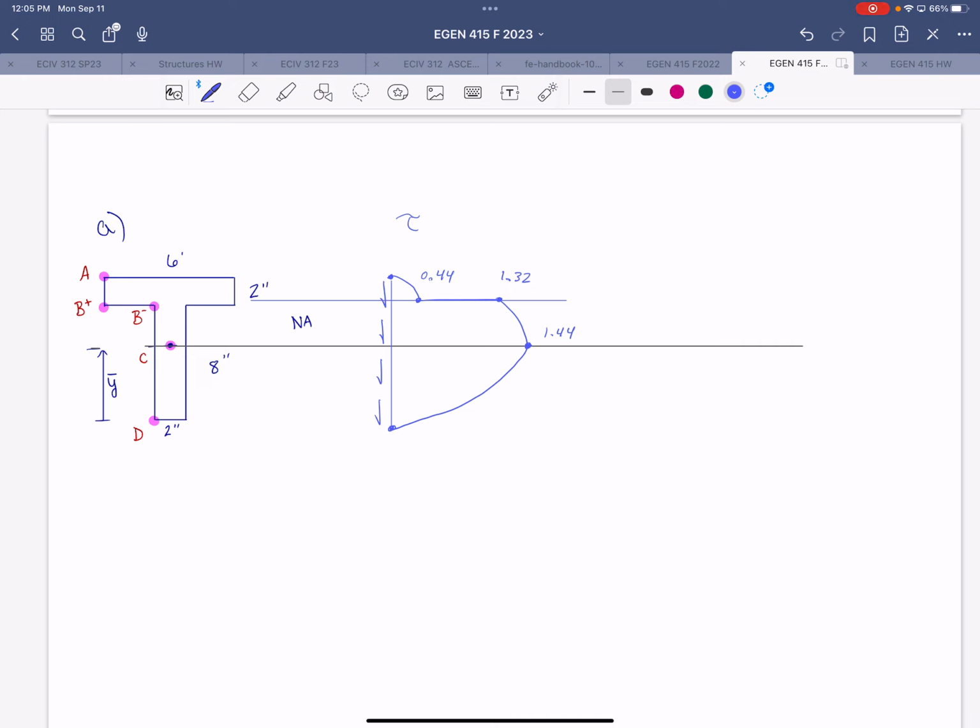So is that positive or negative shear stress in physical space? Think about Mohr's circle and our definition of shear stress sign convention. Negative, right? It's a little bit exasperating because we go from positive shear to negative shear stress in the same interpretation.